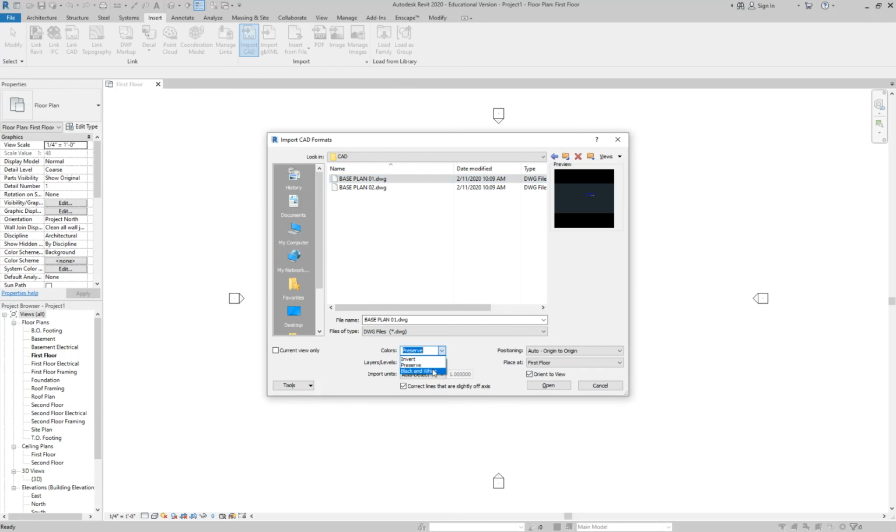So here's something to think about. If I know that I'm going to be turning off my CAD plan, I like to preserve the colors because in Revit, there's no color really, right? So that's an immediate indication that I forgot to turn off my AutoCAD plan. You don't want your AutoCAD plan on for the most part. So after you print, turn it off because now your Revit stuff should be replacing it. Got it?